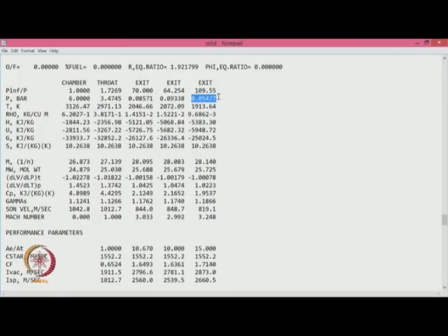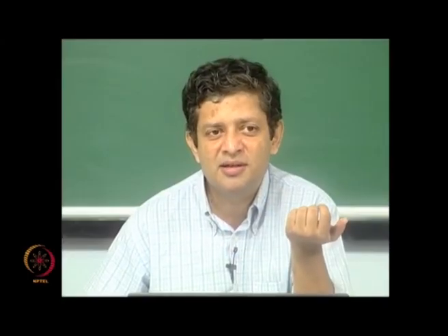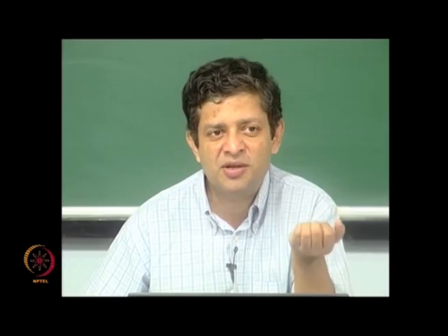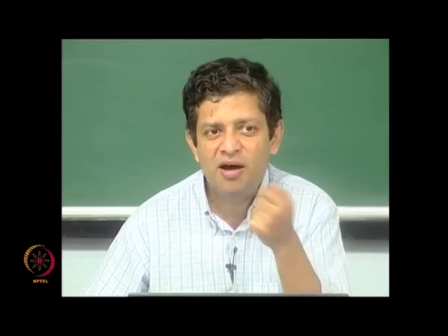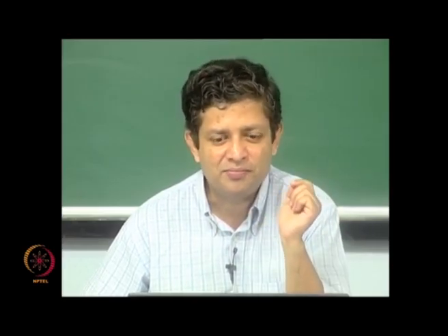Unfortunately this software will not be able to tell you that. So, one needs to be careful and look at the exit pressures while doing this. If you are doing sea level operation, you need to be careful about the exit pressure and use the Summerfield criterion, which is something like 1/3 of the exit pressure is what it can take without any problem.